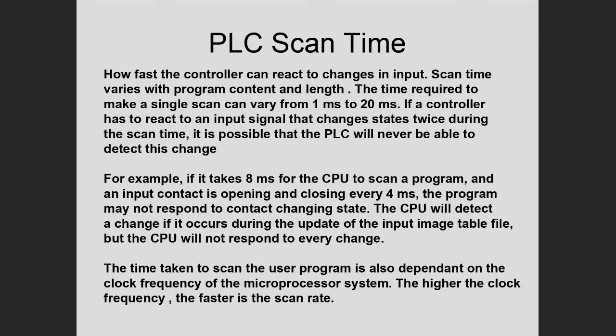The more instructions you have on a rung, and the more rungs you have in the program, the longer it's going to take the PLC to scan. The more switches you have hooked to an input module, the more it has to keep track of in the input image table, the longer it's going to take to scan. And so scan time is important because, imagine this.